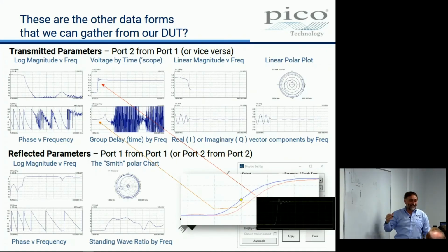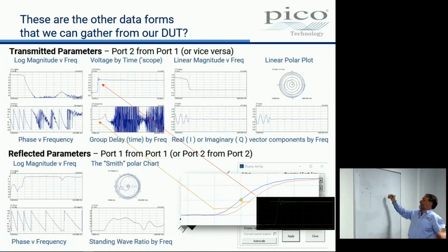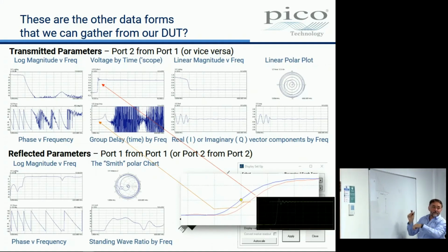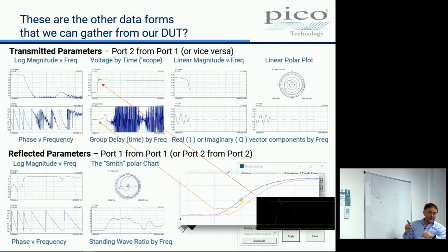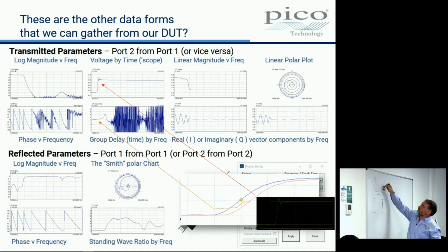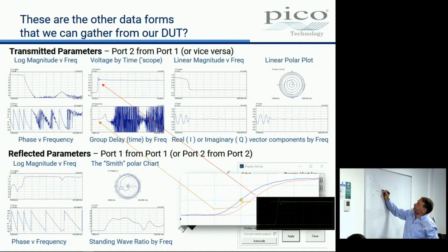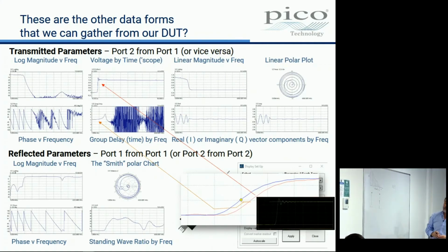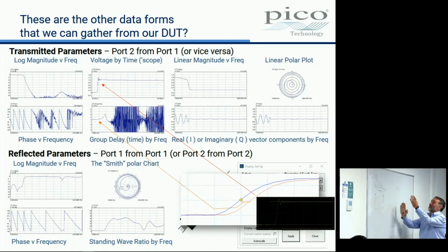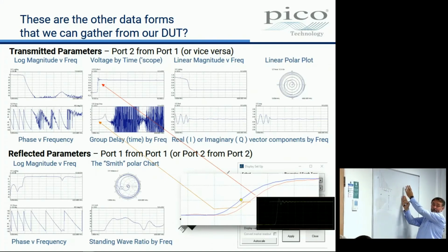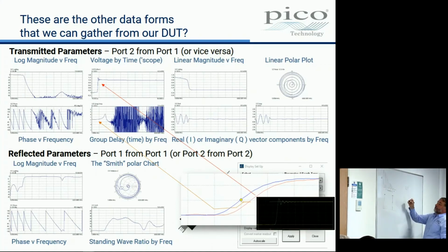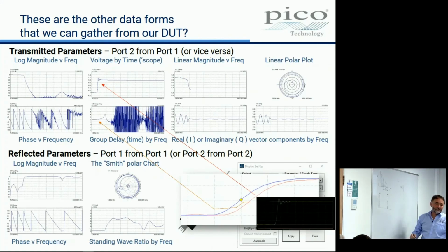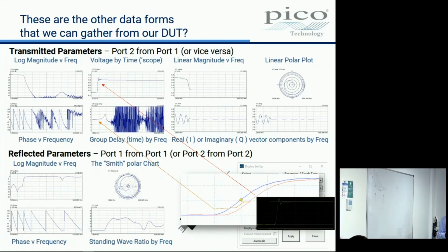I've not drawn this quite right, but all of the harmonics add to make my square wave, right? But what if some of them were delayed by 4 nanoseconds and these were all delayed by 2 nanoseconds? Oh God. All these harmonics are going to start to misalign with one another. And this is what happens.